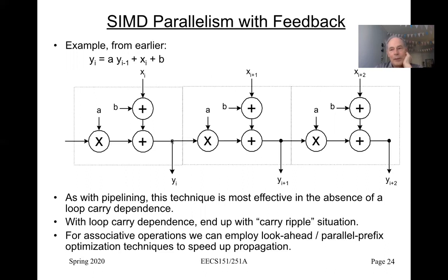It used to be a register. Remember, I told you before that wires in space turn into registers, or wires in time. So before we had this connection, which here is in space, in the serial one, where we're executing the loop serially on one piece of hardware, we had a register in there to make that connection. Here it is just a wire.